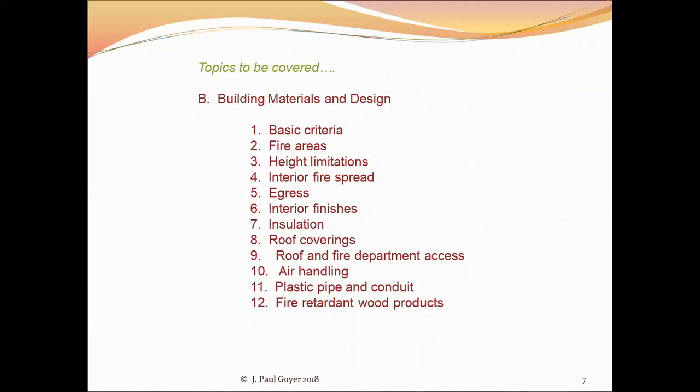In a larger, more sophisticated contemporary building, the controls on the air handling system might, as an example, shut off the primary air moving fan in the system, and through a system of dampers and controls, perhaps a second fan will come on, or maybe the primary air moving fan will remain functioning, but the air from where the fire breaks out is exhausted directly to the exterior of the building.